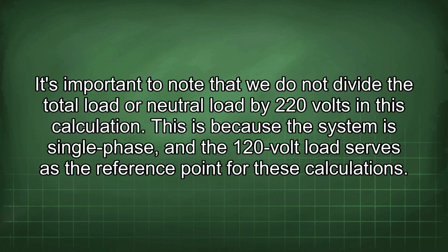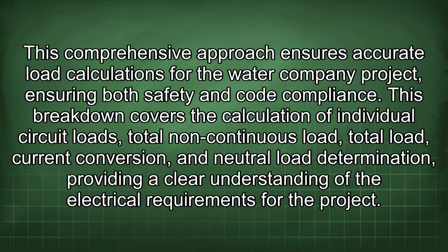It's important to note that we do not divide the total load or neutral load by 220 volts in this calculation. This is because the system is single phase, and the 120 volt load serves as the reference point for these calculations. This comprehensive approach ensures accurate load calculations for the water company project, ensuring both safety and code compliance. This breakdown covers the calculation of individual circuit loads, total non-continuous load, total load, current conversion, and neutral load determination, providing a clear understanding of the electrical requirements for the project.